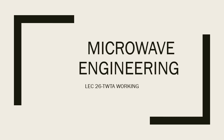Last lecture, we have seen that TWTA has got a lot of advantages as compared to Klystron. It is a wideband amplifier. It's a broadband amplifier. Gives you 60 dB of gain. If you want to increase the gain, what do you do? You just increase the length of the tube.